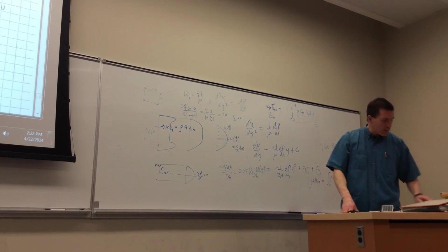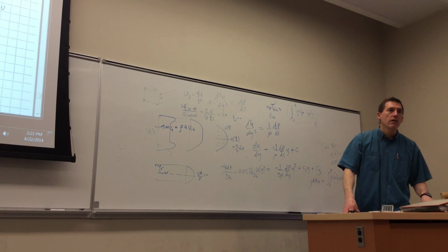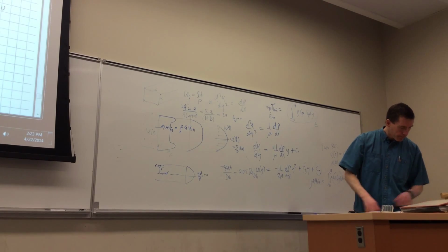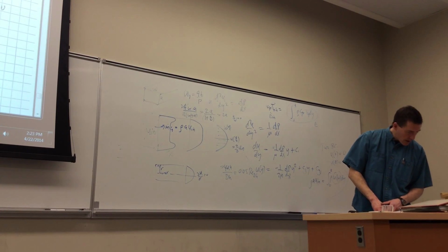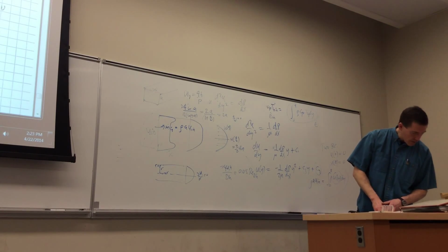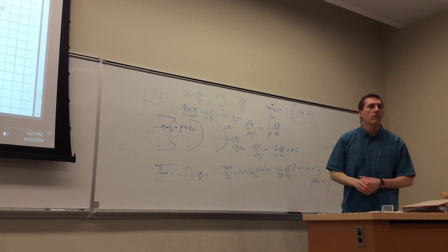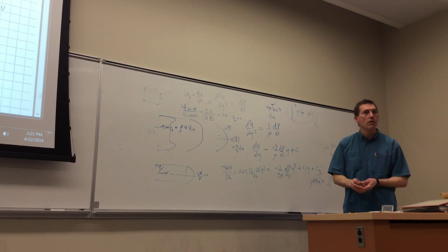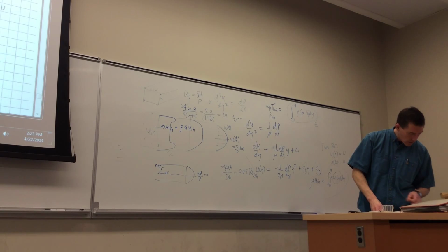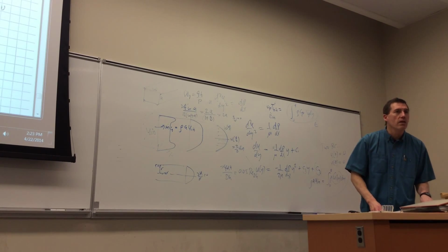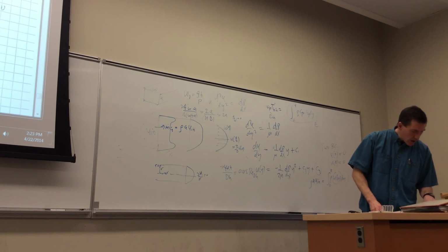I would judge that just by, if I had all kinds of time, I would plot it. But on a test, I would calculate the peak of it and say, yes, my average is less than the peak, so it seems reasonable. And if it's parallel plates, then the peak would occur at spacing over 2, right? Parallel plates is always symmetric. I think for the question, they actually denote the middle as your 0. Oh, the middle is 0. So the peak is at y equals 0 then. Yeah, so the peak is easy then, because the peak on U is 0.75 and the peak on temperature is 5.